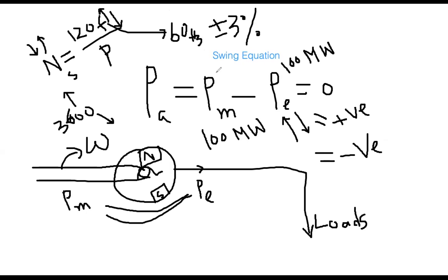You can understand it at your home, for example, when one of the bulbs is blinking. In your kitchen area, the tube light is blinking, your television screen is blinking. That can be the reason: there is a huge change of frequency, some fluctuations going on. That is not desired. But as long as it is within plus minus 3%, that is fine. Once it goes beyond that number, you can visualize it in terms of light blinking or some devices.